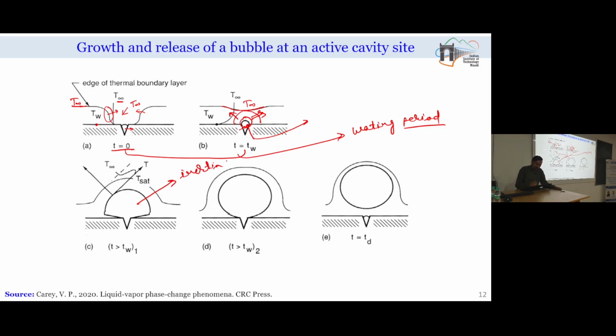So, in this stage, the growth of the vapor bubble will be inertia controlled. We assume that in this range, the degree of superheat of the liquid is sufficient enough that it will not cause any restriction on the growth of the bubble. Rather, the inertia of the liquid acts as the resistance on the growth of the vapor bubble.